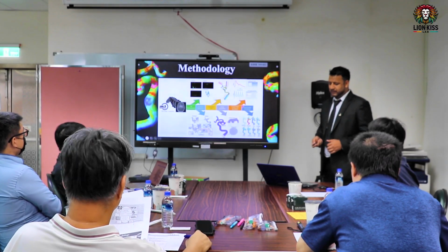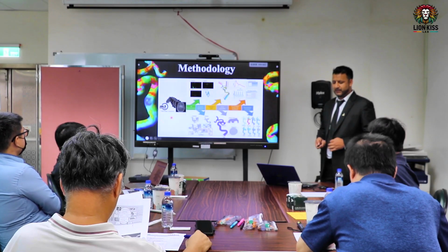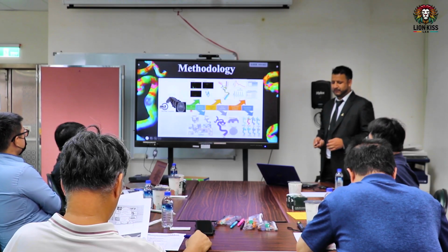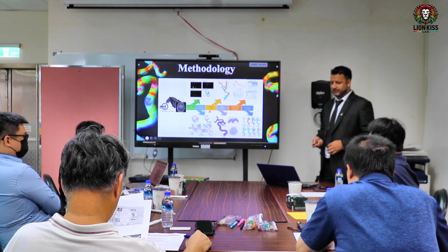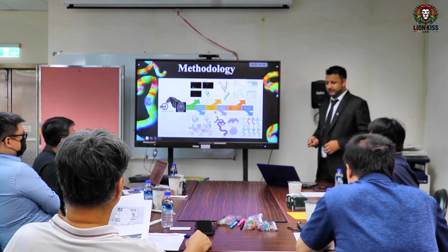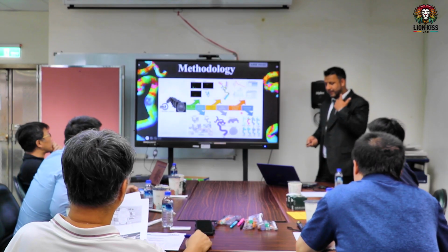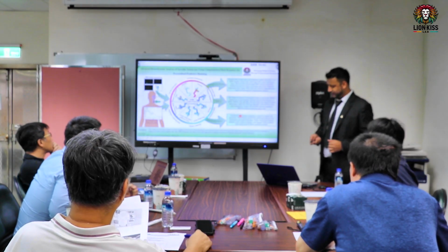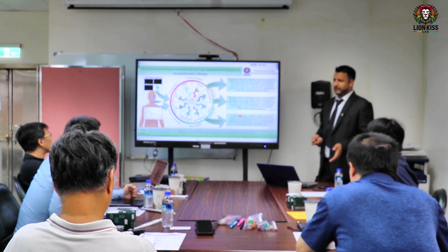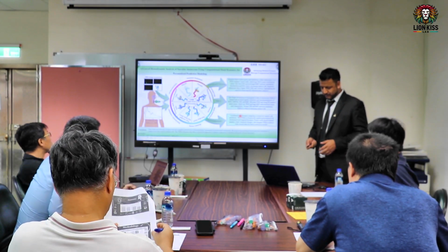So in the cerebrovascular artery, we use MRI images, and the steps are almost the same: 3D reconstruction, refine it, extended tube, mesh generation, CFD simulation. We use the pulsatile flow of the internal carotid artery. After that, hemodynamic analysis. So this is the graphical abstract of my first intracranial artery paper.